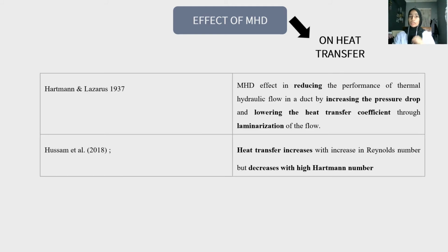Next is the effect of MHD on the heat transfer. According to Hartmann, Lazarus, and Lazarus 1937, the MHD effect reduces the performance of the thermal hydraulic fluid in a duct by increasing the pressure drop and lowering the heat transfer coefficient through the laminarization of the fluid.